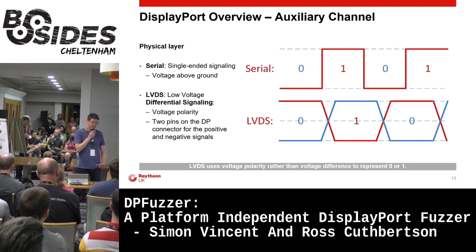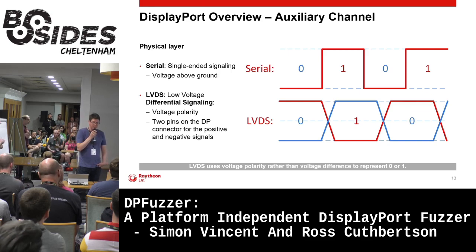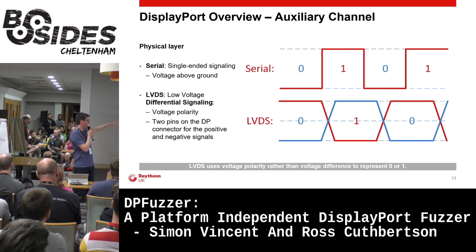At the physical layer, we need to understand the characteristics of a differential signal, or LVDS. At the top, we've got a typical signal from a microcontroller. And at the bottom, we have a differential signal, which is used to carry the auxiliary channel messages. Basically, voltage polarity is used to represent bits on the line rather than voltage amplitude. And the differential signal is used as it supports high data rates, and it copes well with noise.